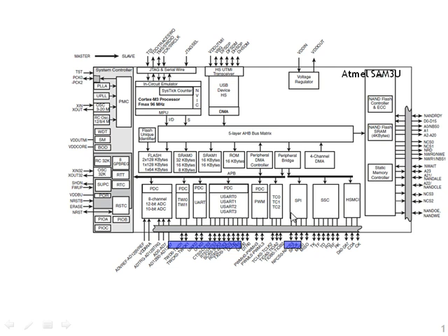So what we're talking about is a subsystem within the microcontroller that has to do with communication to the outside world using high-speed serial buses. Your UART, that's typically used for something like your RS-232 port, or what some people might call the COM port. The SPI, serial peripheral interface, might be used for high-speed communication to chips.